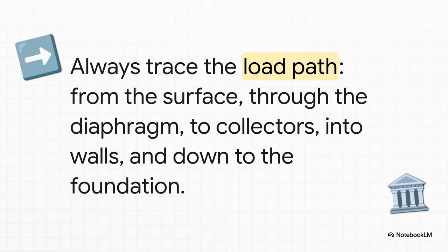Look, if this all feels like a lot to remember, just bring it back to this one single idea. Always trace the load path. For any question on any drawing they give you, your very first instinct should be to put your finger down and trace the path of a force from the surface, across the sheathing, into a collector, down a wall, and into the foundation. If you can do that, you've got this.